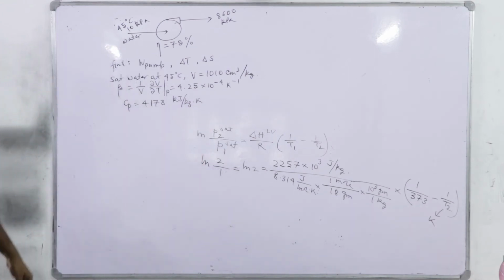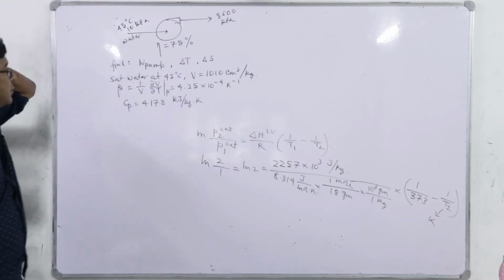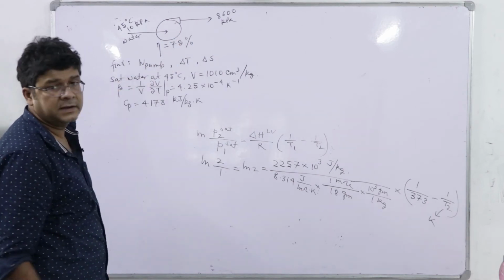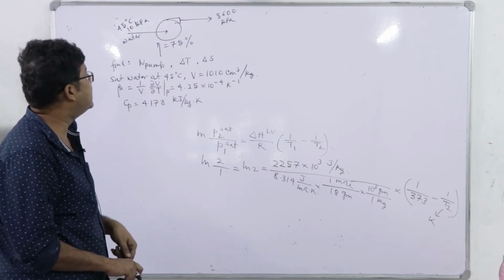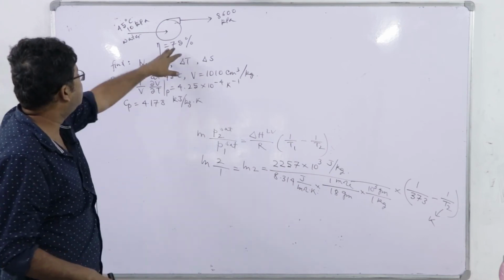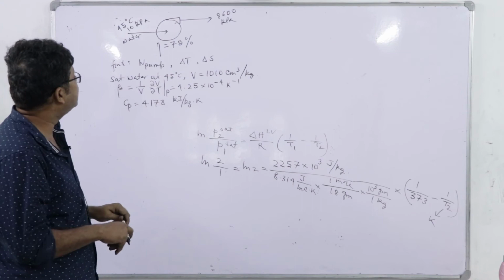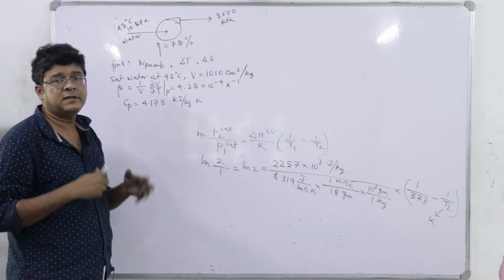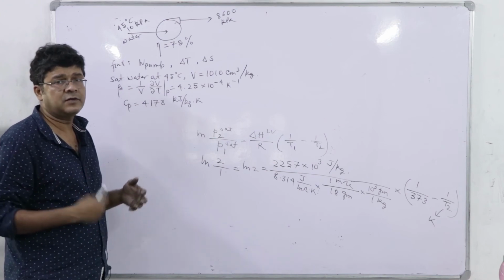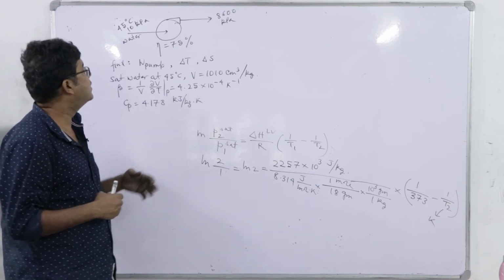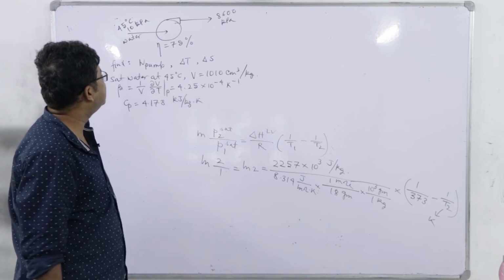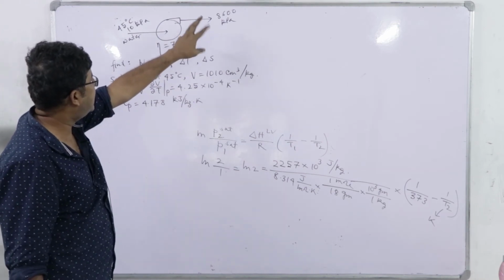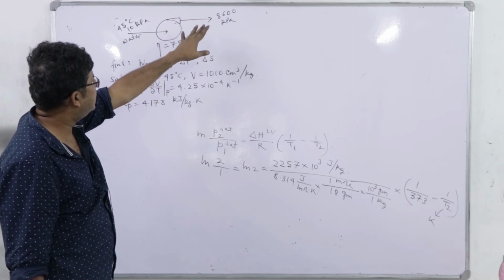Right. So, basically we have to get the equations for delta H and delta S. And this efficiency is not the typical pump efficiency we have studied in fluid mechanics, it is with respect to isentropic process.